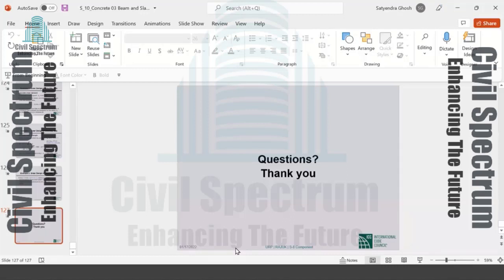How should I say, you have to be doubly careful in designing those transfer girders in seismic areas. If you prohibit transfer girders, you are restricting the architecture of buildings to an extent that is really not warranted.